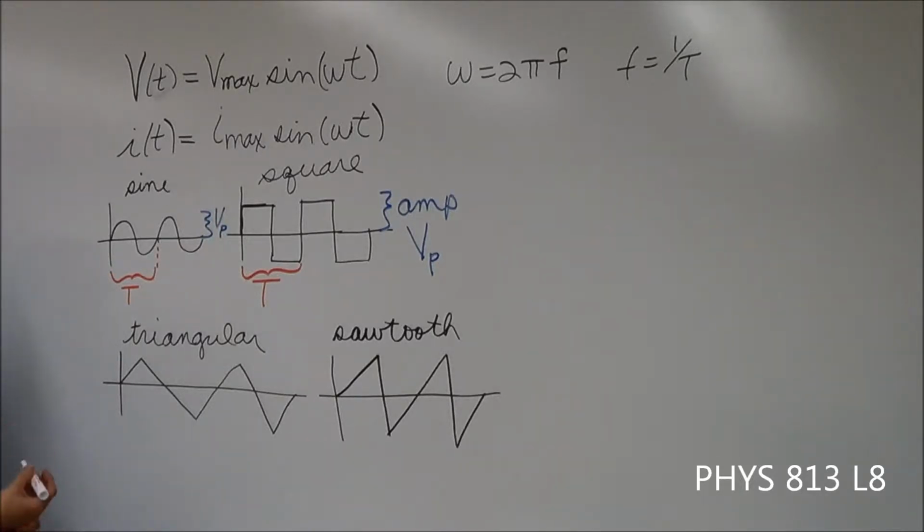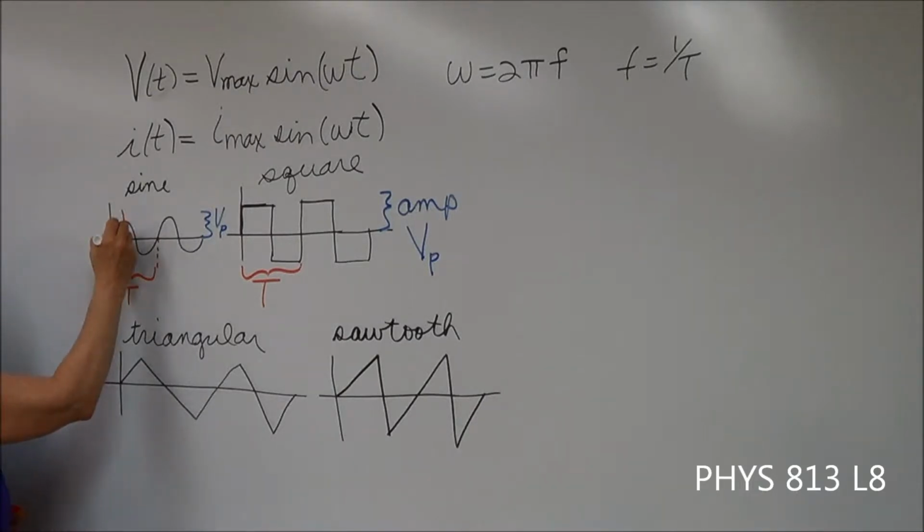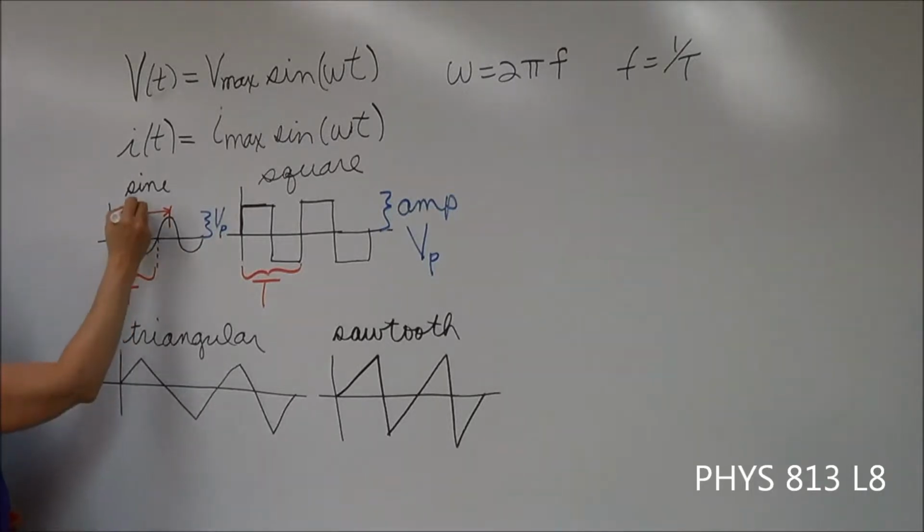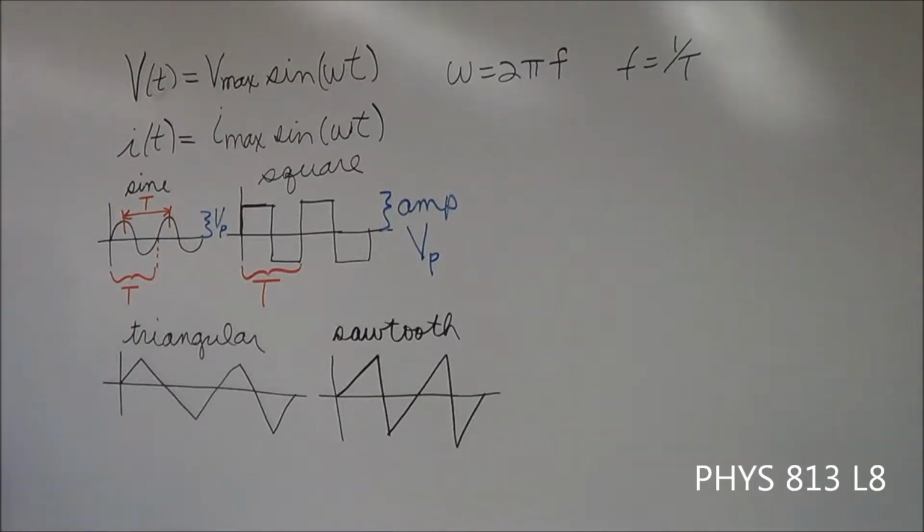When we're actually measuring on the oscilloscope, it's going to be easier if we measure from peak to peak horizontally. If we look at the time there, we also get the period. Now we're going to have to keep track of what you're measuring, because when you look at this, you see centimeters, you see a distance. But on the oscilloscope, the distance represents either voltage or time. And the two that we're going to use quite a bit is the vertical.